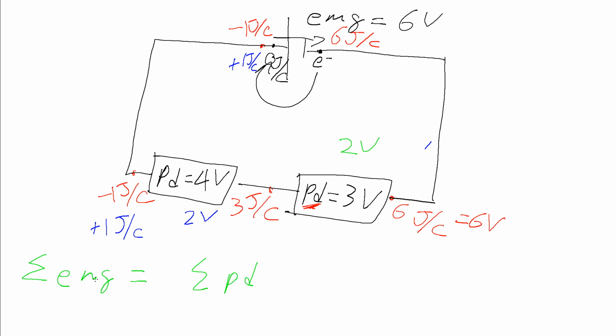So the sum of the EMF in is the sum of the energy out. And remembering that these are voltages, that's energy per charge, so for a given charge, energy in equals energy out, just the conservation of energy. So just as Kirchhoff's current law was actually nothing more than a manifestation of the conservation of charge, Kirchhoff's voltage law is actually nothing more than a manifestation of the conservation of energy.